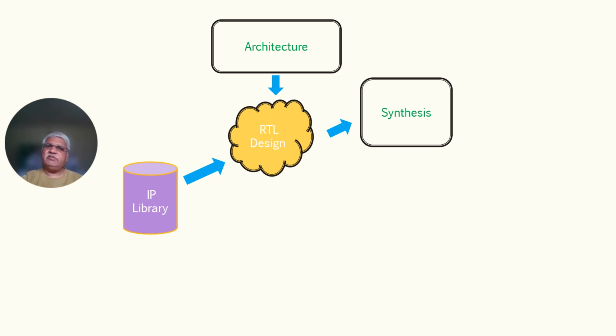So coming to the power estimation, the RTL design is also used to estimate the power. What IC design is doing is, whatever is possible, they are checking it at the RTL phase. The reason being, as we have figured out earlier, if we do many fixes at the RTL design, then the cost of implementation is low.